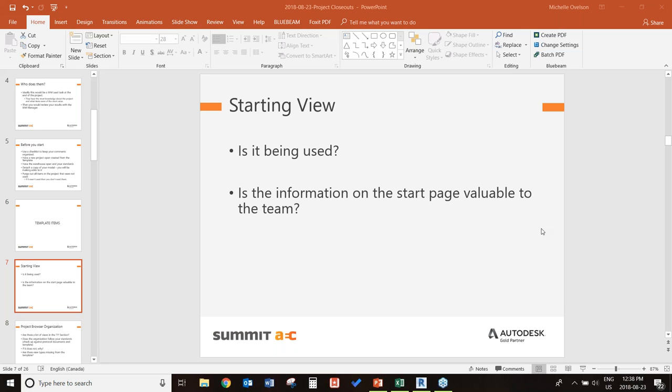an in-place family. That's usually what I use as a flag, because it's not necessarily about whether they're using an in-place family. If it's a one-off thing that had validity for being in place, then that's fine. Where it becomes a problem is when they take in-place families and copy them 20 or 30 times. So without doing anything complicated, just looking at a schedule of families will give you a very quick rundown if they're being used where they shouldn't be.